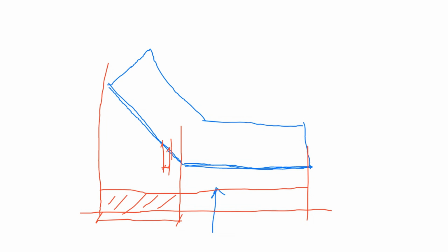Instead of this, we will come to the building and draw our elevation looking at it from the side, and chop here and crop here. That is one elevation, and we come to here and draw another elevation, and crop here and crop here. We'll come here and draw this. Of course, if I apply the same concept, I will see this and a portion of this, and I do not project that, so I stop here and stop there for my elevation, and I come here and draw another elevation.